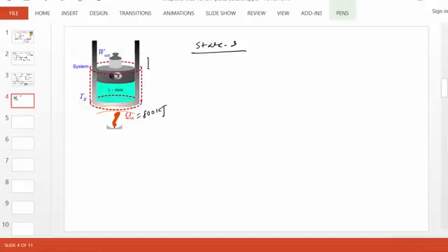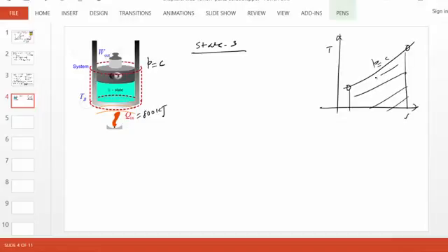So this time pressure remains constant. How does the process look? In the TS diagram, recall, it is similar to the constant volume line, except the constant pressure line is a little bit less steep, and the area underneath is proportional to the heat that is added. So what do we know about this state? Pressure doesn't change, so 180 kPa. Of course, we have already evaluated mass. Mass doesn't change.